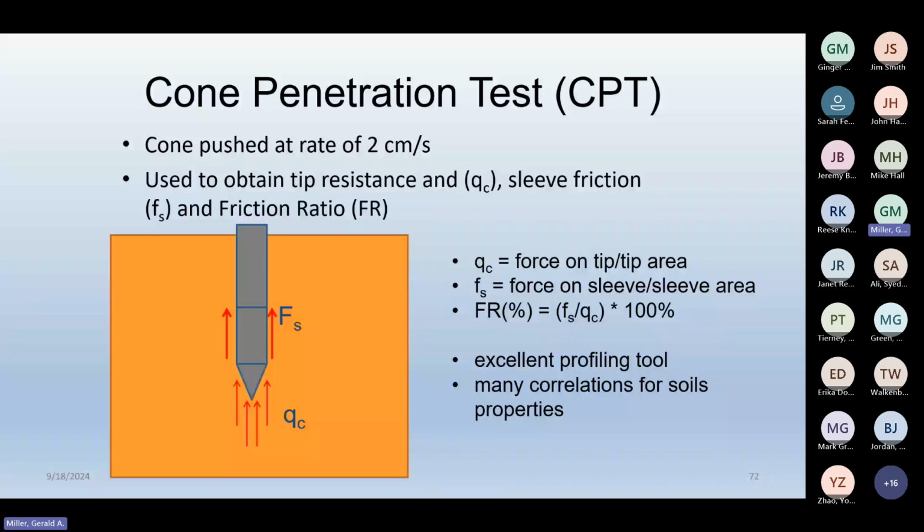Then we would lower it in the hole under the water, and take off the protective cover that was holding the fluid in there. So it never saw air. That's how careful we were about keeping that pore stone saturated. So there's no question that when you punch through an unsaturated profile, you're going to remove fluid from your sensing element.